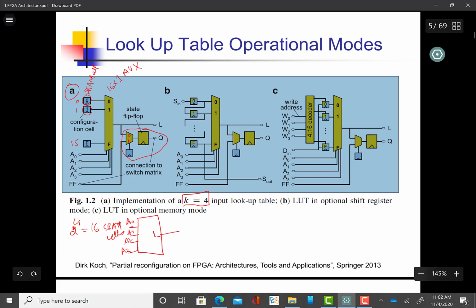So you just need to program this mux with a 0, which will select the output of the LUT and it will be passed to a flip-flop. So you can store the output for 1 clock cycle if you configure the SRAM cell here with a 0, for example. So this is how you implement a combinational logic.